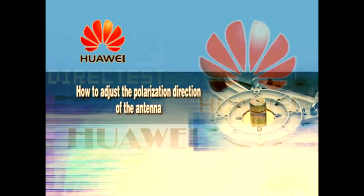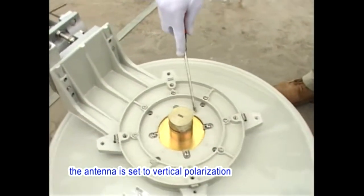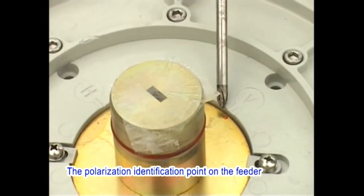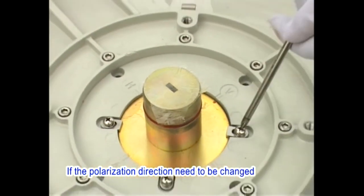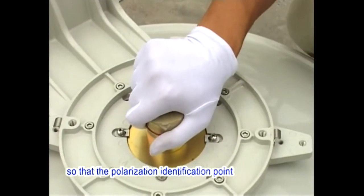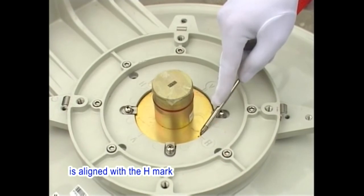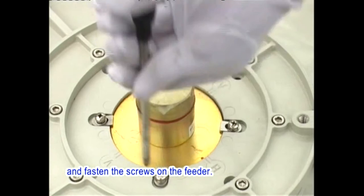How to adjust the polarization direction of the antenna. By default, the antenna is set to vertical polarization. The polarization identification point on the feeder should be aligned with the V mark. If the polarization direction needs to be changed, loosen the screws that are used to fasten the feeder and rotate the feeder 90 degrees so that the polarization identification point is aligned with the H mark. Stop rotating the feeder and fasten the screws on the feeder.